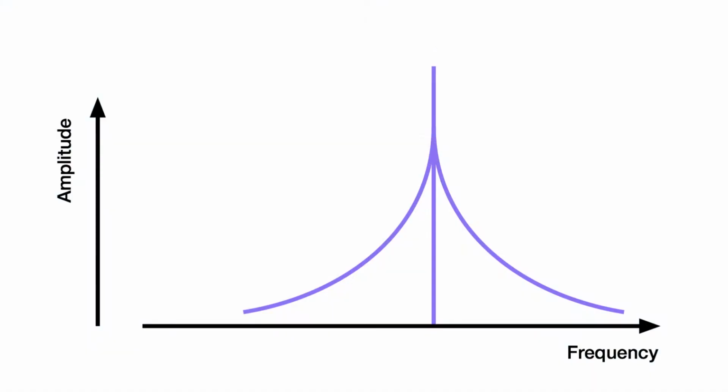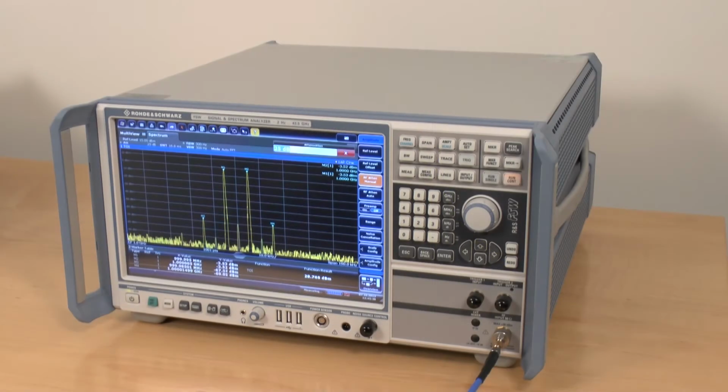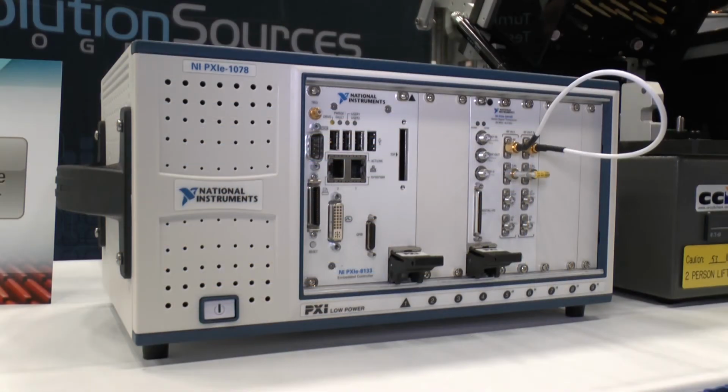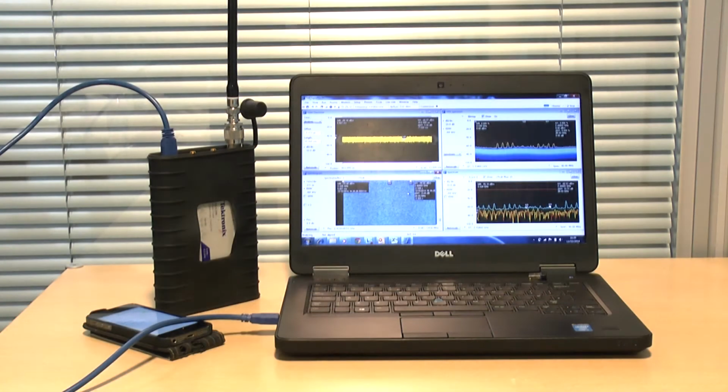Systems with poor phase noise performance may exhibit an inferior bit error rate and not carry data as well, and they can also affect users on adjacent channels. As the phase noise performance of signals is so important, it's necessary to be able to measure it. The easiest way is to use a spectrum analyzer, and there are many different types on the market, from boxed ones to those using PXI chassis and others using USB connections to computers.